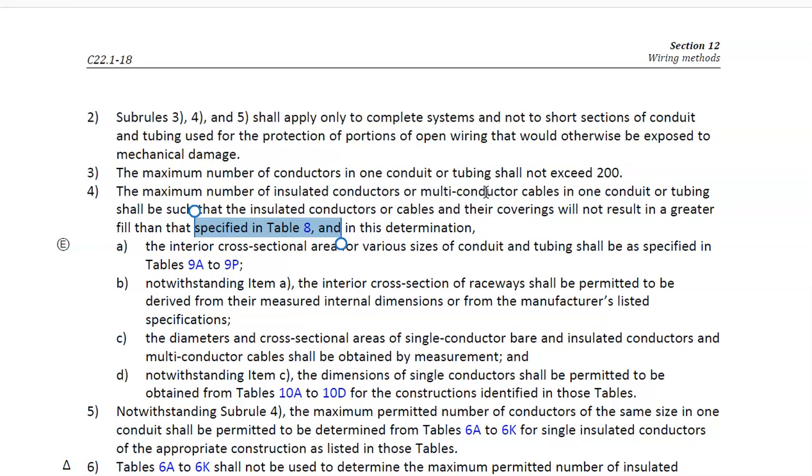Now, normally, I don't go to D1 first. Usually, I'm just going to look at a chunk of cable in my hand in front of me and say, hey, the jacket of this thing says no more than 300 volts, so I should probably not go more than 300 volts. Anytime that there's conflict between your D table and the cable jacket, the cable jacket always wins. The tables are designed as a general catch-all for anything that you don't have access to inside of the field. But usually you want to err on the side of first checking what is on the actual cable jacket itself.